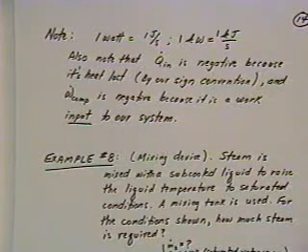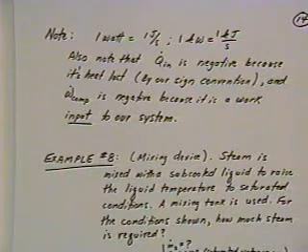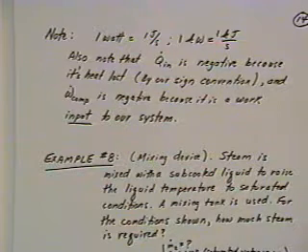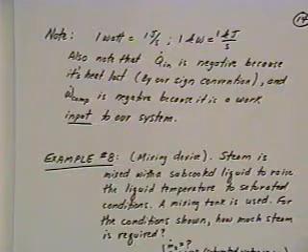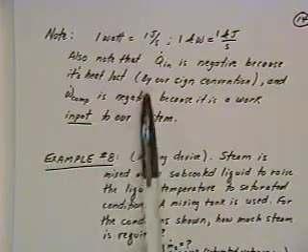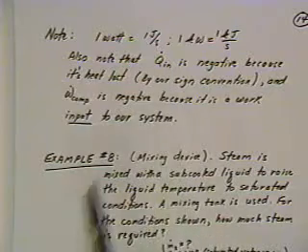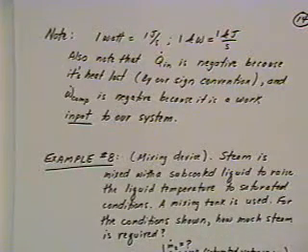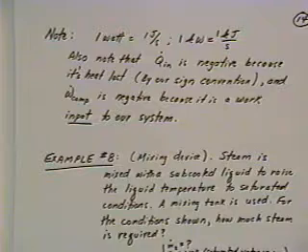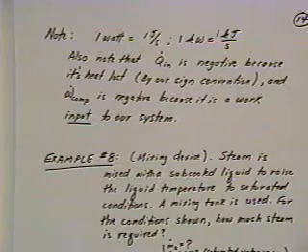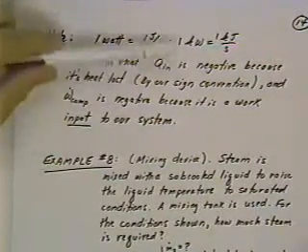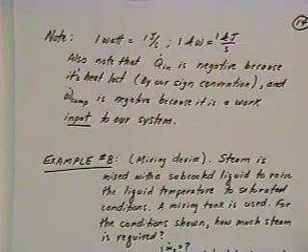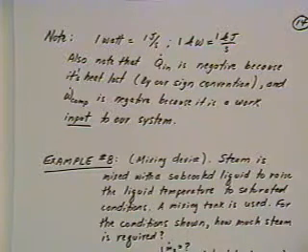You've got to make sure that the units are always compatible, and some of you may be used to working in SI system and metric system and be very familiar with that. Others may not be, and so you need to really practice and get familiar with the SI system. We already pointed this out when we were going through the problem solution, but Q dot N is negative because it's heat lost by our sign convention, and the work of the compressor is negative because it's a work input into the system. And so just a couple of reminders here dealing with unit conversions and also making sure that you're familiar with the sign convention.